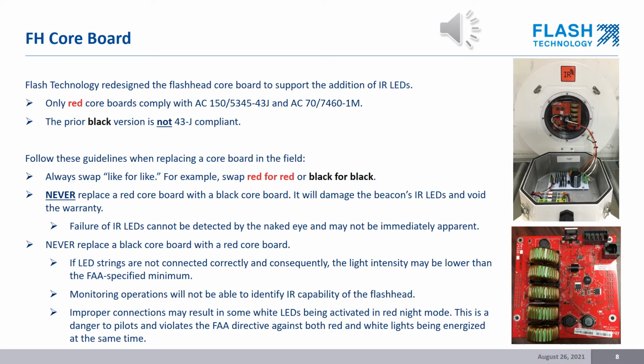Always swap red for red or black for black. Never replace the red core board with a black core board. It will damage the beacon's IR LEDs and void the warranty. Failure of an IR LED cannot be detected by the naked eye and may not be immediately apparent.